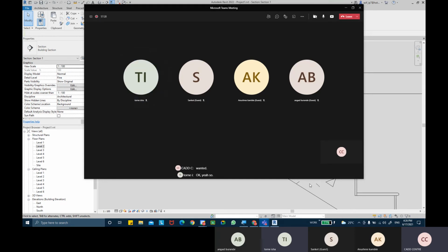So a little disadvantage is there in this Revit actually. They have not fixed this bug yet, the fixing of the landing with the waist slab of the staircase. To resolve that temporarily, what we do is we just create a landing of the staircase and then we connect it. Okay. So in the next class we will start with the project, so we'll understand more clearly about this type of staircase landing and connection of the slab.